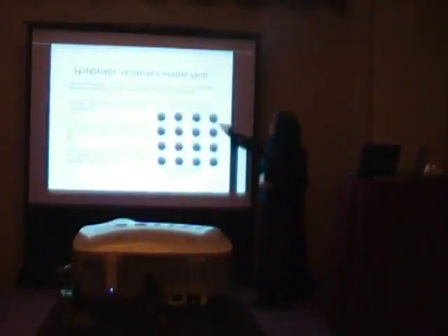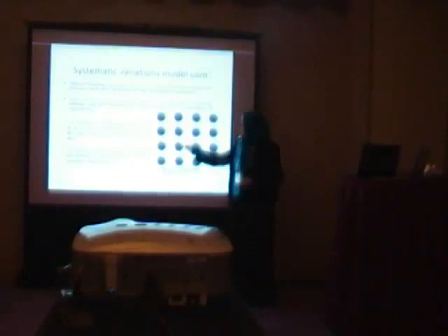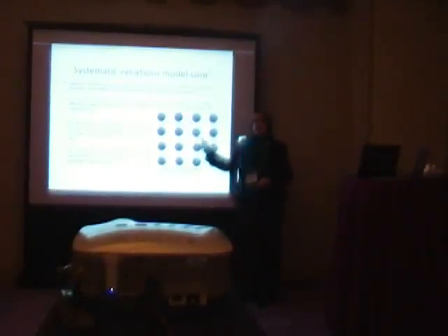If we superimpose these variation maps on the NoC floor plan, we will get the delay of each link depending on where it is on the die. So at this position, we have a value for this region, L_G, W, and T_ox.